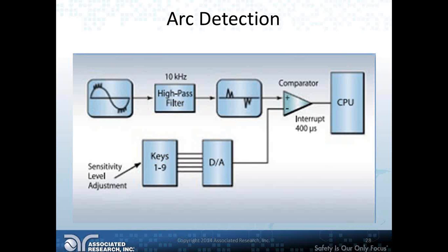The arc detection failure displayed by the high-pot tester is separate from a high-pot failure or a high-limit failure or a breakdown that occurs during a high-pot test. So do not confuse arc detection with high-pot, although this is a feature within the high-pot test that can be activated or deactivated depending on whether you are looking for arcing conditions or not.